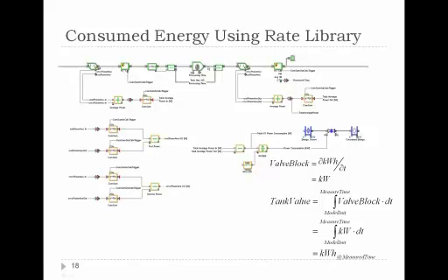If the item has processing time, it's going to be processed for a certain amount of time. Subsequently, on the exit, the same thing is happening. The amount of service and tool power are summed up, and once again, we're using an information block to trigger the calculation. This is the total power in and total power out. The total power in and out are subtracted from each other, divided by 1,000 to convert watts to kilowatts, and we're looking at the power consumption through this rate block through a tank, an input tank, and an output tank.